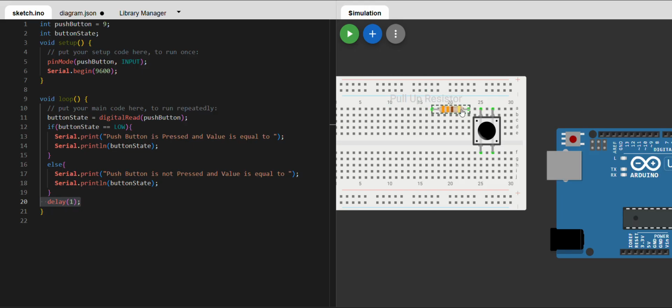So you shouldn't make it vertically. Why? Because if you make it vertically, this particular pin and this particular pin are in the same shorted line, so the resistance will be shorted, right? So you have to make sure to make the connections properly on the breadboard while you are going to perform this mini project on the breadboard. So let's discuss the next thing.